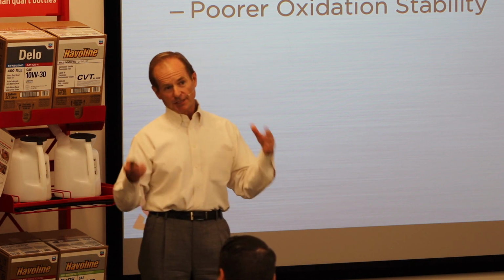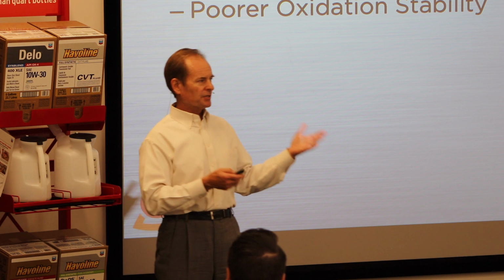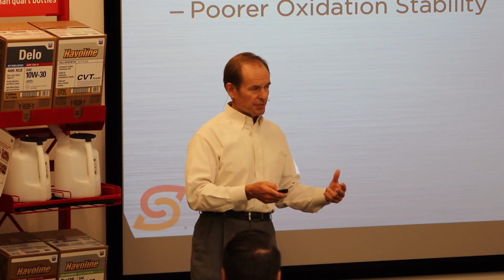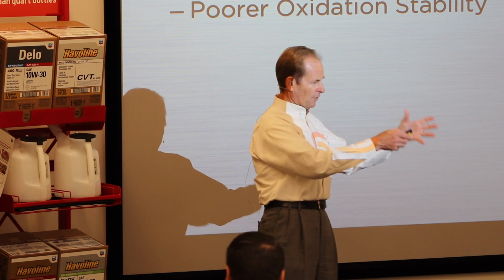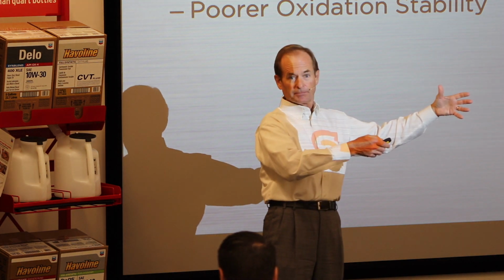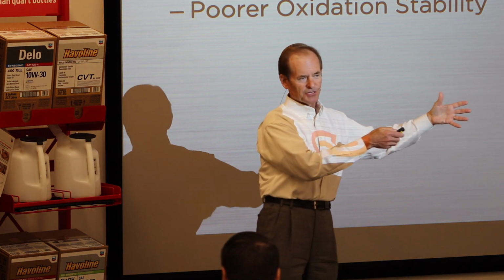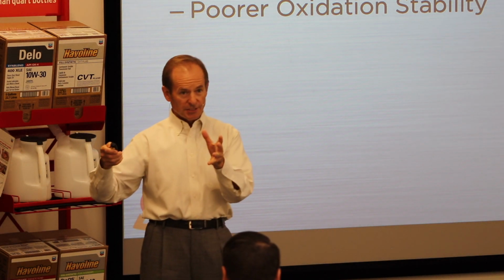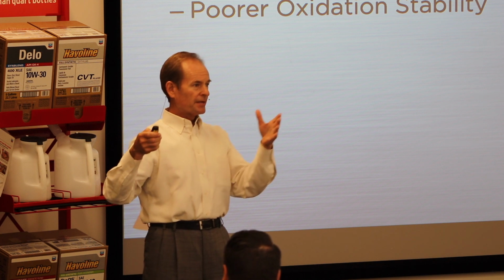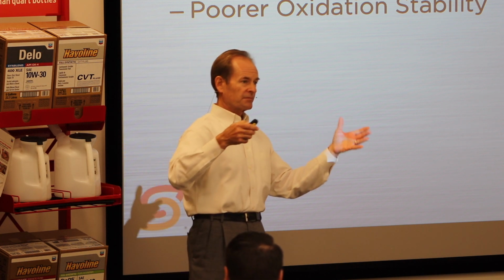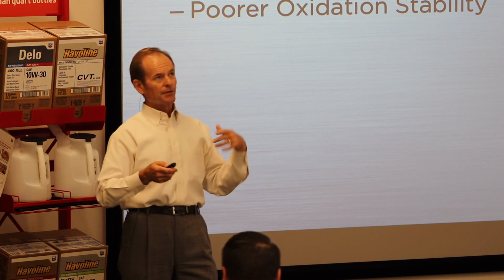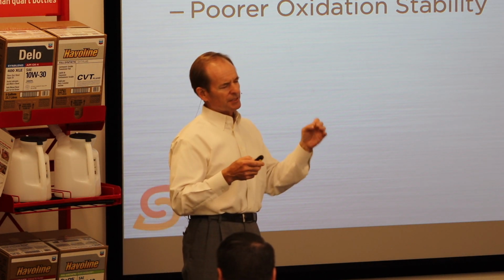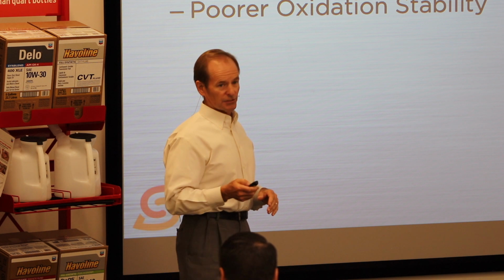There's a number of reasons that greases are more susceptible to oxidation than oil, including things like, to manufacture grease, you take your oil and you put it in this big kettle and you heat it up, right? You've already started the oxidation process. And then some of the chemicals used as thickeners in your grease help promote oxidation. So you're already halfway or part way there. So this oxidation stability is not as good in grease as it is for an oil.